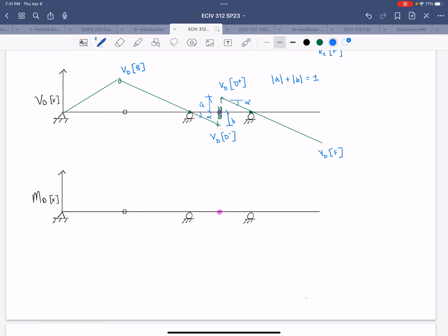All right. And then last but not least, the moment at D. So we add a hinge at D and force it through a unit rotation. If we force it through a positive unit rotation at D, that's going to make that hinge point move upward. So we're going to have a positive displacement at D, and that's a hinge, so it can change slope, which is good because that's the only way we can meet these support conditions on either side of it.